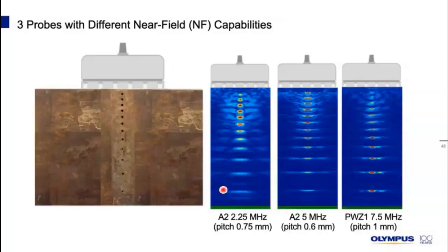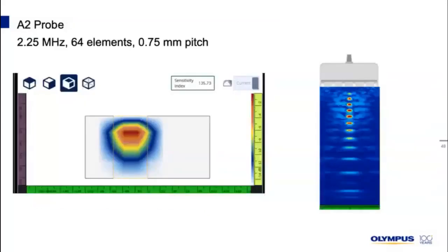So again, the same 3 probes that we had earlier. It's just like with phased array, it is not possible to focus past the near field. Even if we do say that we are focused everywhere, if the probe is not capable of that focusing capability, then it's impossible to have a zone that will be focused everywhere. So we need to be very aware of the limitation of the probes. So here's how AIM can help here.